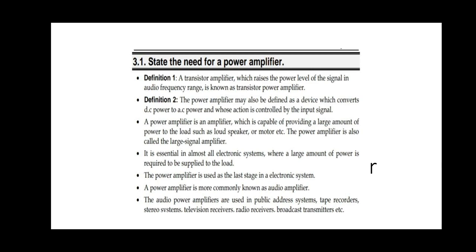Just as distortion is divided, noise is also divided. NF equals N by 1 plus A beta, where N is the open loop noise, NF is the closed loop noise. So the noise in the amplifier with negative feedback, NF, is divided by a factor 1 plus A beta. It increases the input impedance and decreases the output impedance depending on the sampling network and mixing network.